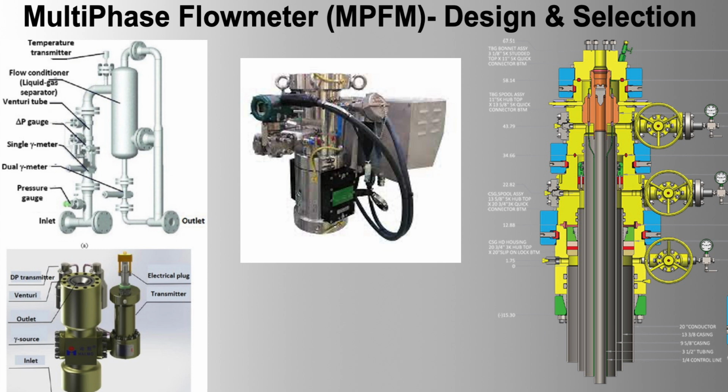2. Onshore well testing. Flow meter type, impedance-based multiphase flow meter. Material, Inconel for high corrosion resistance. Installation, horizontally installed with robust supports to minimize vibrations. Calibration, in situ calibration capability to ensure measurement accuracy. 3. Subsea application. Flow meter, electromagnetic multiphase flow meter.